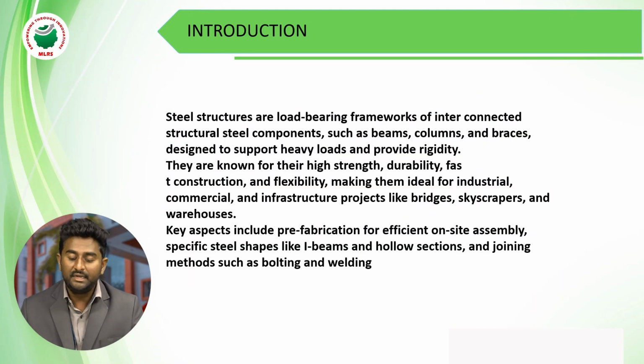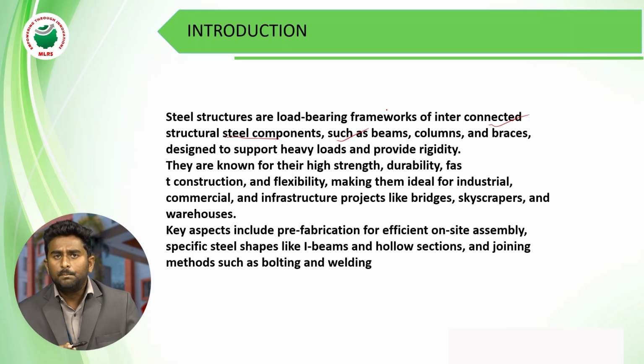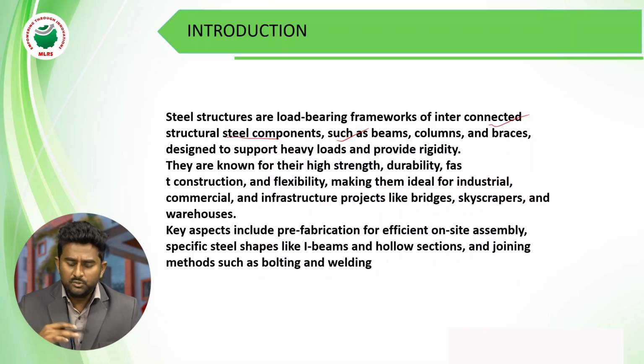Steel structures are load-bearing frameworks, interconnected structural components such as columns, beams, and gusset plates, with bolted connections, welded connections, riveted connections. These components are connected to the footing with the help of gusset plates. Below the ground level, you have to provide the substructure. You have to construct only the RCC structure. Above the ground level, for the superstructure, you can use only steel structures.